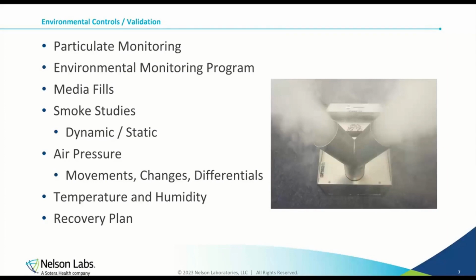Smoke studies, both dynamic and static, when you're in operation and when you're not in operation, so that you can see the airflow, that you still have control and your HEPA filters are still working and the air pressure is right and the movements, and you're doing nothing in there to contaminate product. Temperature and humidity are monitored, and if anything goes wrong, typically you have a recovery plan.